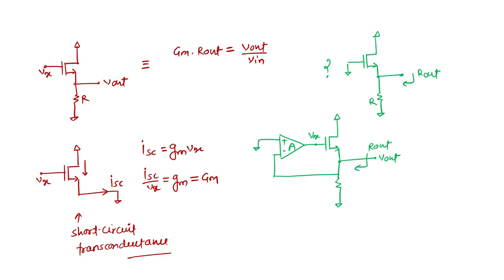Because what we are seeing here, let's see the GM and all these terms for the transistor again. I should do the calculation again. This calculation from the GM is not that exact because the gate is connected to this gain block as well. So we will do the GM calculation and the R out calculation. Both calculations will give me the direct input to output gain. Then we'll see, if we calculate the gain separately, what the effect will be.